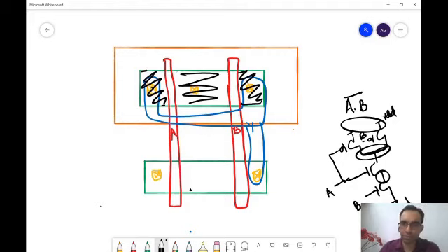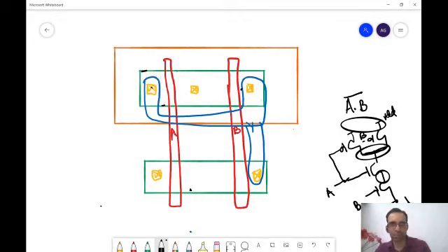No, sir, but this area will come because it is source. So source area is also coming, right? Because we cannot think of only the drain area. Source and drain both come. On the output, whatever area you connect, that is the area that will come, right? If my device, if my wire is here, why would the capacitance of this node appear on my output?